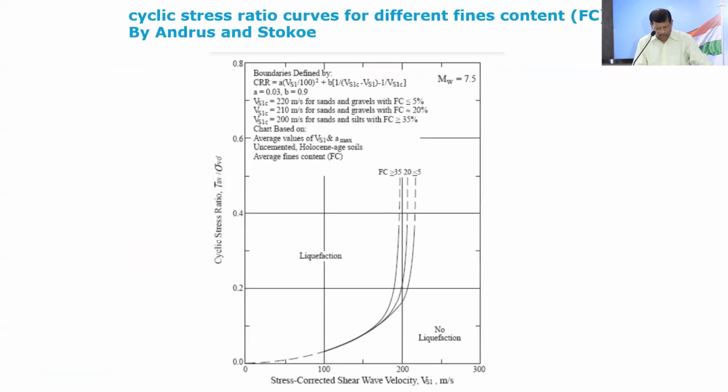This is one of the examples which we also follow. There is another example also. We have the M value. Based on the M value, most of the seismologists and also the seismic engineers would model, because SPT value is the only parameter available. So it is based on the SPT data, but mainly for the tailings, I mentioned that the SPT value is very confusing. It is very difficult to do that. So that's why we use the shear wave velocity. That's what we get from our CPT data.